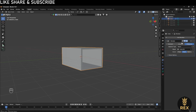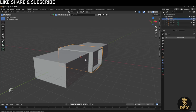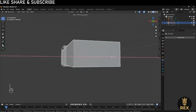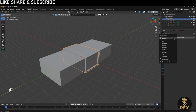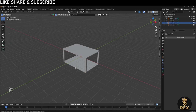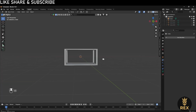So now we will apply this, and now I will make this, hide it and increase it in the X axis. Then I will do Boolean again with the same object, same method. I'm choosing this, then hide, and see that I get the same result again. So this will do this.